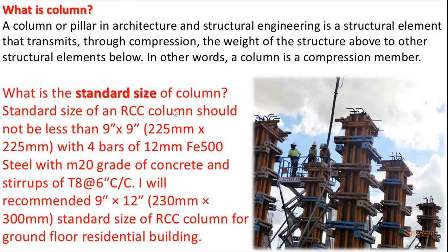What is the standard size of a column? The standard size of an RCC column should not be less than 9 inch multiplied by 9 inch, with 4 bars of 12 mm Fe 500 steel, M20 grade of concrete and stirrups. Recommended 9 inch multiplied by 12 inch is the standard size of an RCC column for a ground floor residential building.